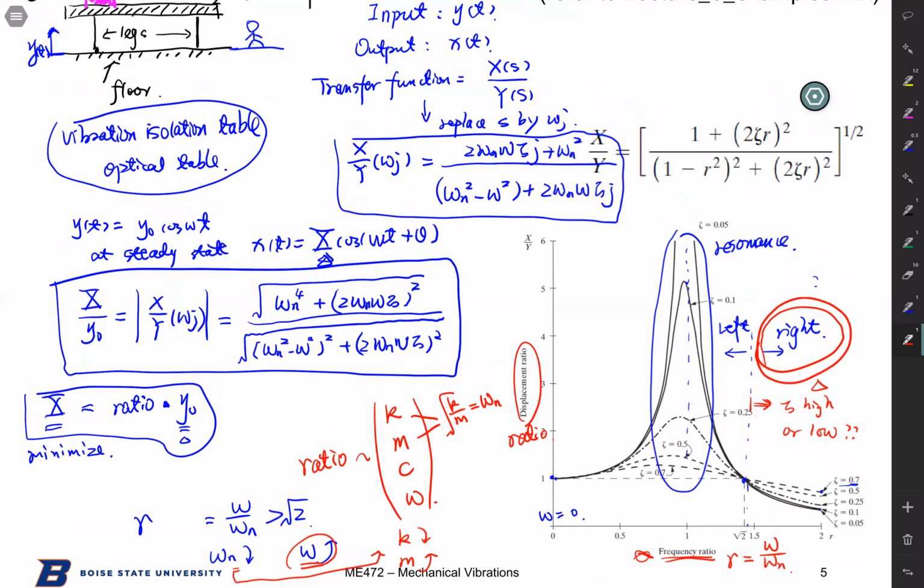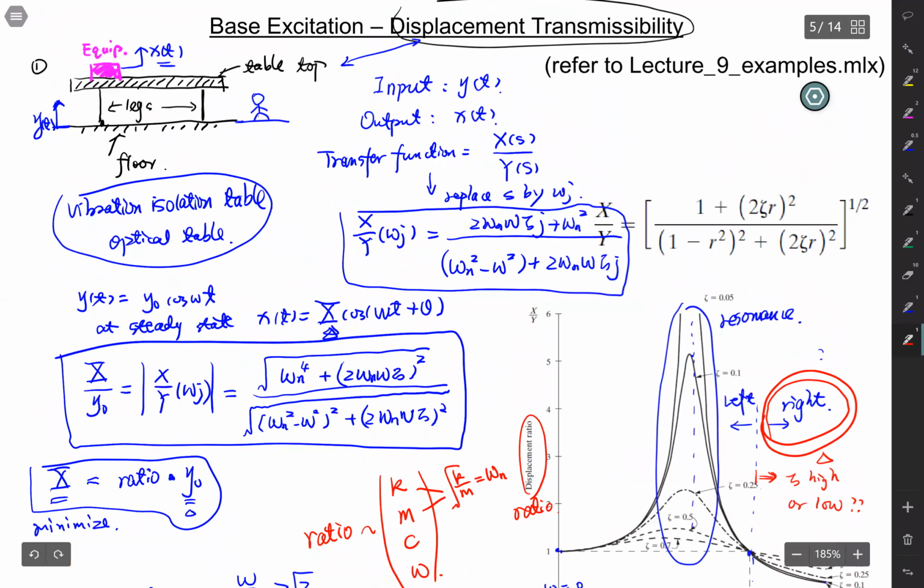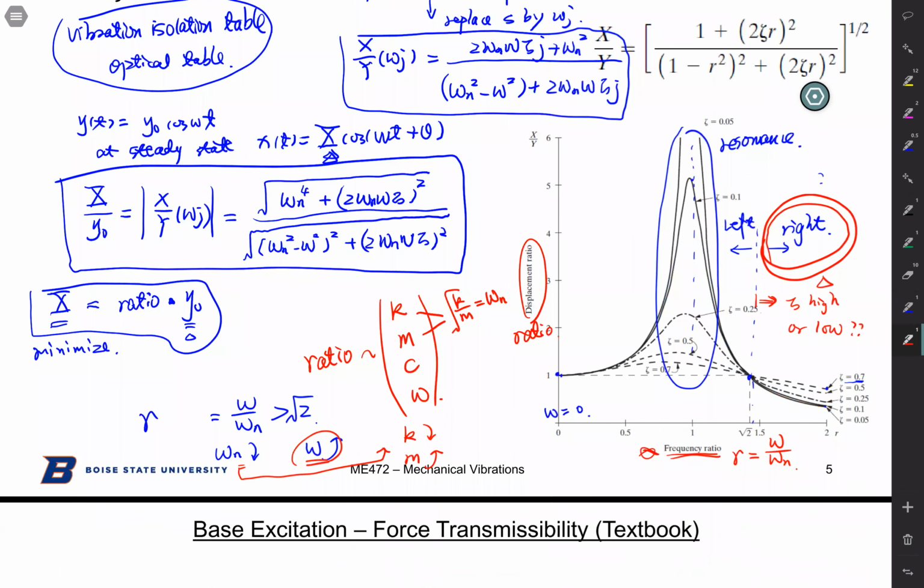So that's why, yeah, if it's not online teaching, hopefully I can show you the vibration table in my lab. So that table is actually pretty huge. The tabletop is actually made of stainless steel. It's pretty heavy, perhaps a few hundred kilograms, half a ton or something. It's a huge mass floating on 4 pneumatic supports. So in practice, your spring support will be some pneumatic cylinders, and then your mass will be a stainless steel tabletop.